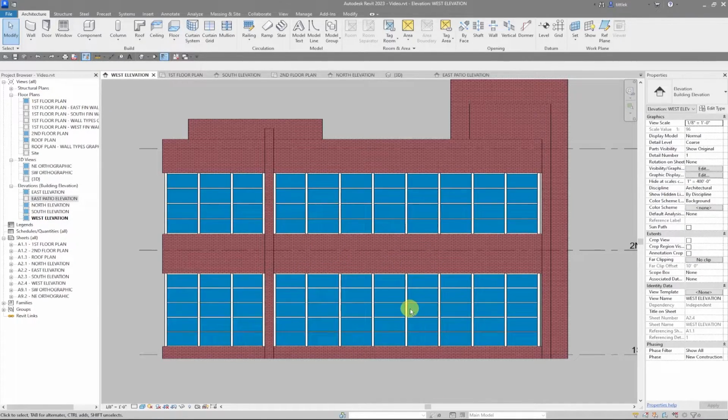So again, when I go back into the plan to actually place the dimensions that locate these, they will not be over constrained. The other thing that I've done, which I want to remind you, is that I've aligned all of the grid lines from this section of curtain wall to this section of curtain wall and locked them using the padlock icon. And I've done the same for the windows above to the windows below. So all of these things have parametric relationships to each other.